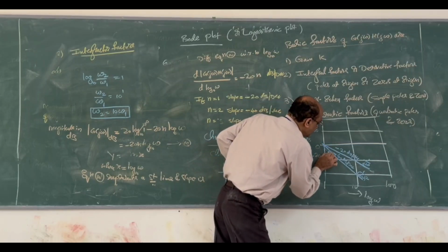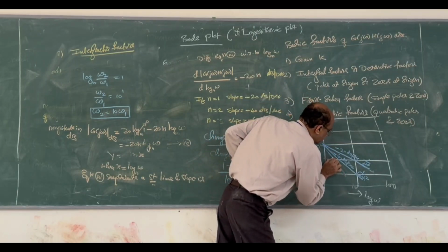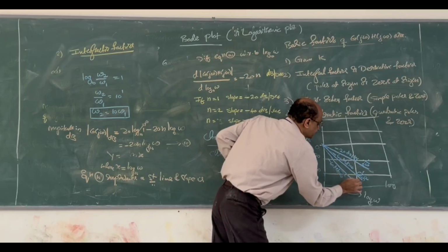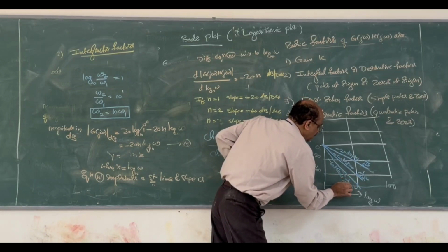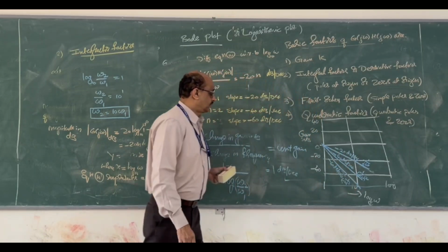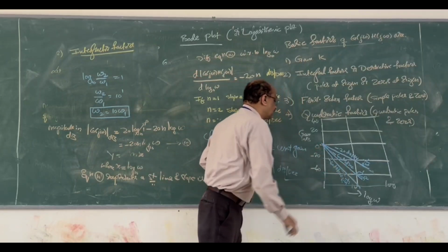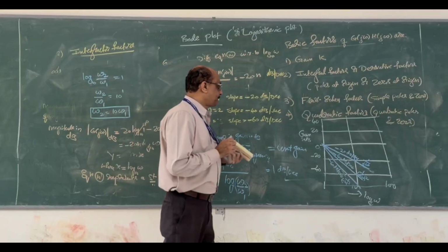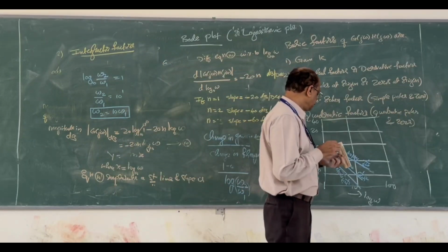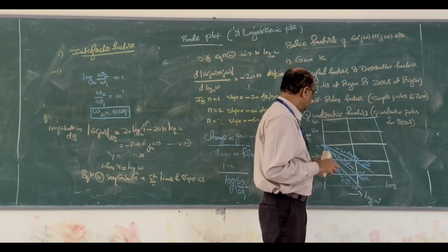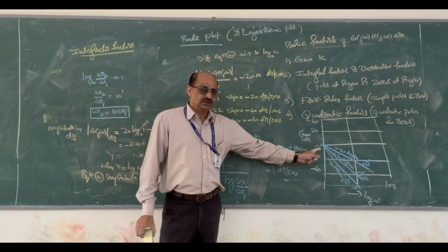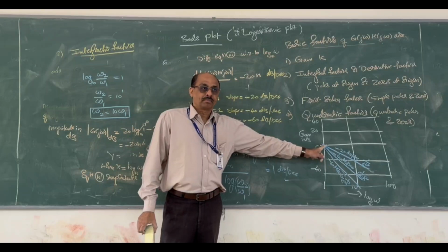So it is from 0. I will now plot. The line joining these two gives you minus 60 dB per decade, and that is for 1 over (j omega) cube. I hope you understand that. Is it clear?